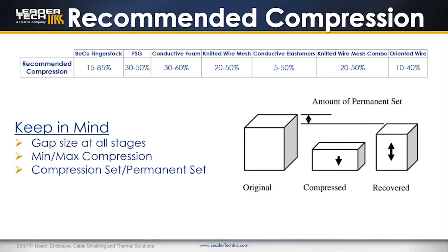Compression set and permanent set is also possible, and for some materials may occur within the recommended compression range. Depending on the size, temperature, percentage of compression, and the amount of time compressed, the material may not rebound fully to its original height. This is compression set. For some applications, such as low cycle or permanently closed gaps, the compression set may not affect the application.